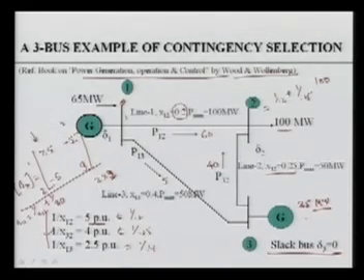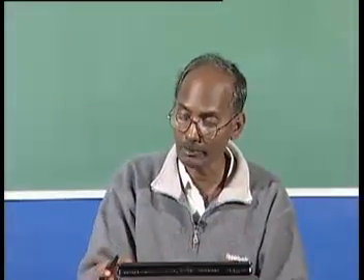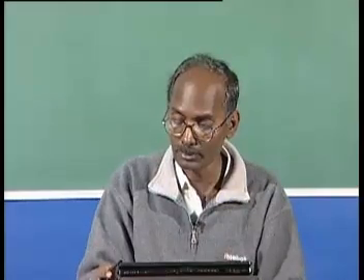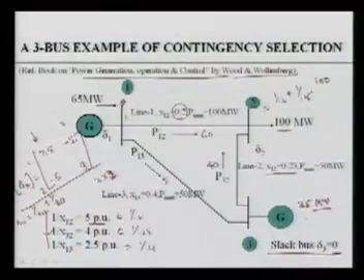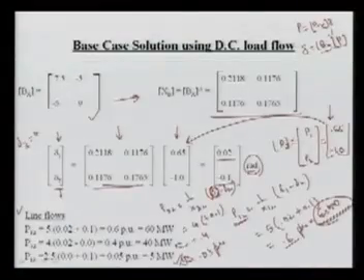So this is the application of what is called non-iterative DC load flow. We can calculate the power flow very easily by simply solving one iteration. Here we are taking only one iteration for one contingency. However, if you are going for the full load flow, then every time, if 4 or 5 iterations are needed, you have to iterate accordingly. So this is one way that we can obtain the line power flows.